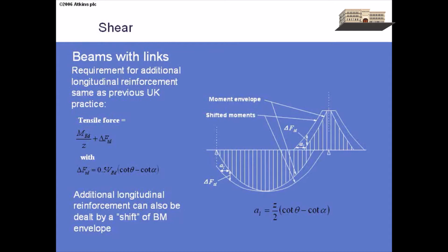If you've got a longer span and you're stepping your longitudinal reinforcement down from 40 to 32 to 25, it will push your curtailment points out. So in that situation, you will actually be physically providing more longitudinal steel in the span to suit putting fewer links in, if that makes sense. So there's a lot of power to the designer to decide where you want to put the steel, and you need to understand those things to be able to design efficiently. It's also quite a powerful assessment tool as well, even though I come back to where I started, which is you're not really supposed to use it for assessment, but there's no real reason why you can't use that particular clause for assessment.